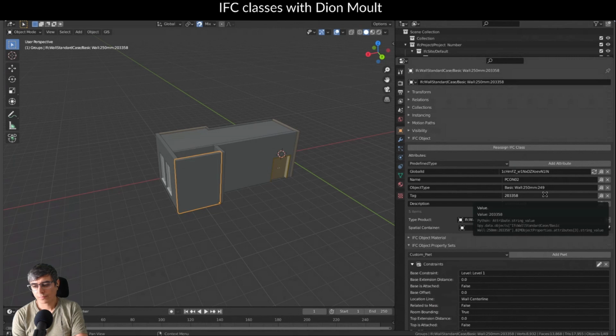And that's exactly what I do find in there. This looks like a Revit element ID in there. And if this came from ArchiCAD, I would expect to find an ArchiCAD element ID, I forget the term for it, but they're equivalent of element ID. So that's the rule. In general, as a user, you should not touch the tag field.